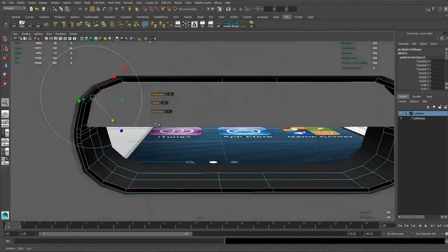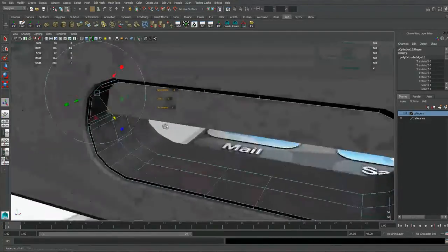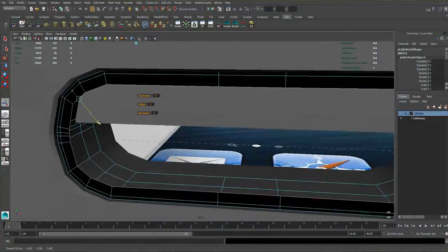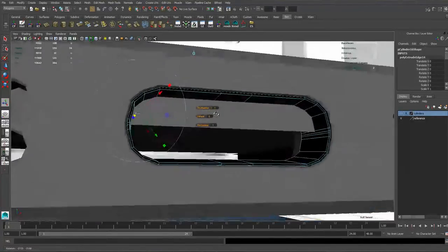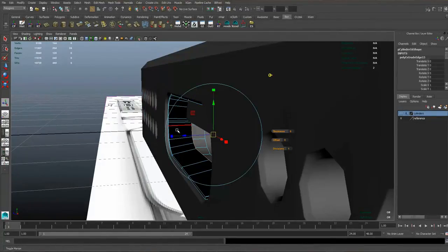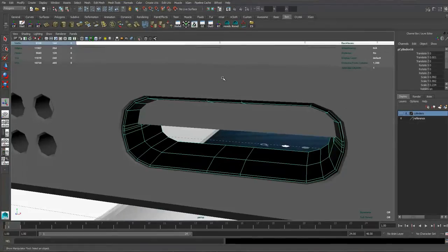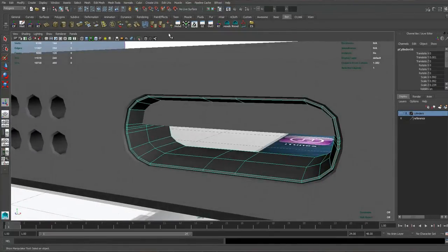Now, what we're doing was actually making this shape inside out, so it's gone black, which means we need to reverse the normals later. Put that to about there, hit G, just to about here, and push it down into the phone a bit like that. That should be fine. Then hit G and snap to grid and push it directly into the phone to there. I'll see how that looks later. Let's just click on it and then go to normals and click reverse, and it should no longer be black. We can also just select the whole object, press soft edges on it all.